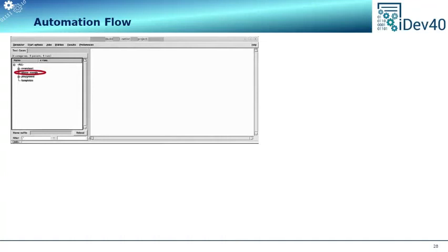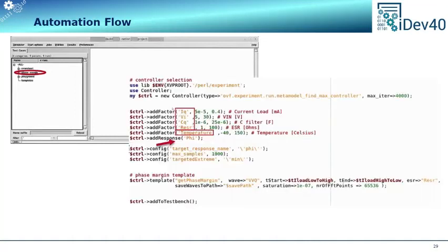The automation flow must be started from a Linux terminal, resulting in the following graphical user interface, able to detect the simulation setup containing the netlist and other necessary files to run the experiment. Next, the Matlab-based adaptive verification algorithm must be configured using a configuration file. It specifies the parameters to be varied and their ranges.